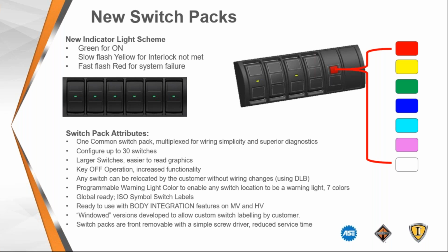All right, this depicts with the red modules some of the devices you may find that are integrated on our chassis. One of which would be the RPM or remote power module. Like I say, you can order 1 to 3 on a truck, or should I say 0 to 3. After it leaves the factory, the truck equipment manufacturer can outfit them with, I think, at least 3 more. Depends on the truck model. So with this option, you're going to get 6 generic switches inside the dash that are going to control 6 outputs depicted by the brown connector and the red wires on that remote power module.